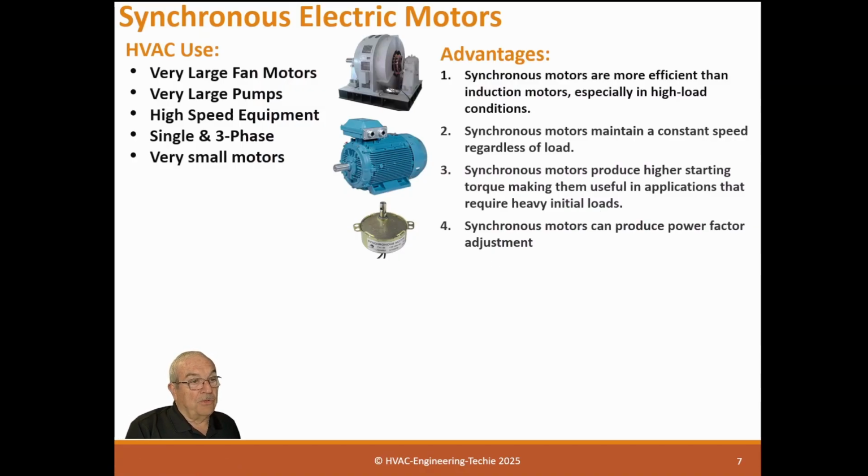So a synchronous motor, you can actually adjust them to improve your power factor. If you have a power factor down around 0.88, 0.86, and you want to improve it, and you have a synchronous motor, you can adjust that motor up to a power factor of 1 or 1.1, and you can actually have it take care of that power factor problem by doing exactly opposite what an induction motor is doing, which is the angle for the use of the induction motor is negative, and then we can make it positive. We can actually change the power factor in a building with a synchronous motor.